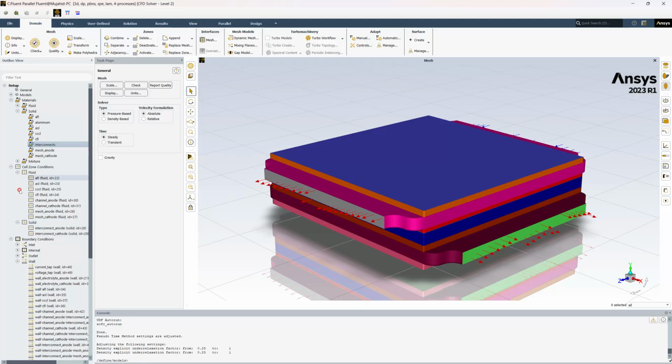Now we need to apply those on the zones, and with the zones we need to specify the porosity of the material. Remember that when we define the materials, we give the bulk, the skeletal density, not the density including the porosity.